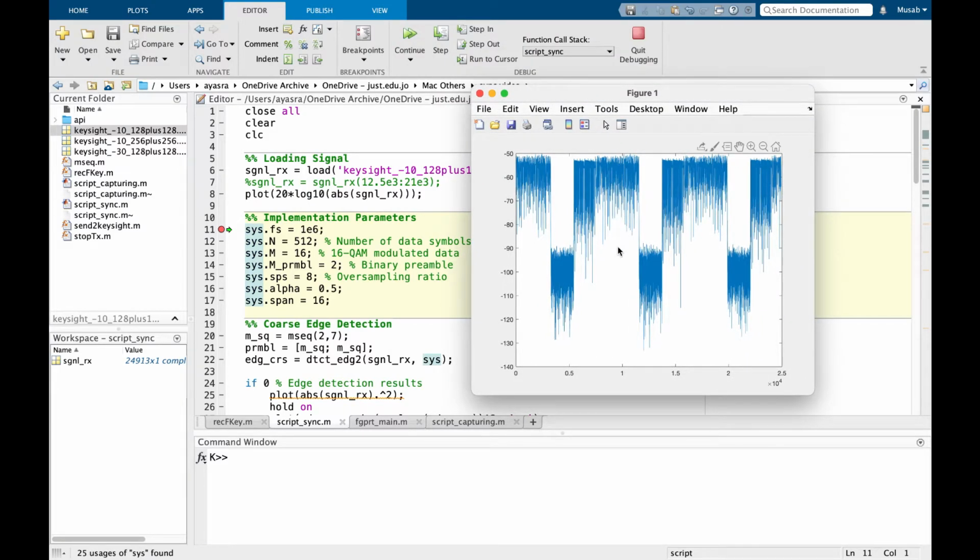This is the signal. The receiver is adjusted to capture a burst with time equal to the time of 3 frames. As we see here, this is 1, 2, and a portion of this frame and this frame, which together is equal to the time of 1 frame, in addition to the gaps for sure. Now, since they are identical and I'm only interested in the synchronization process itself, regardless of the data, let's capture manually one of them.